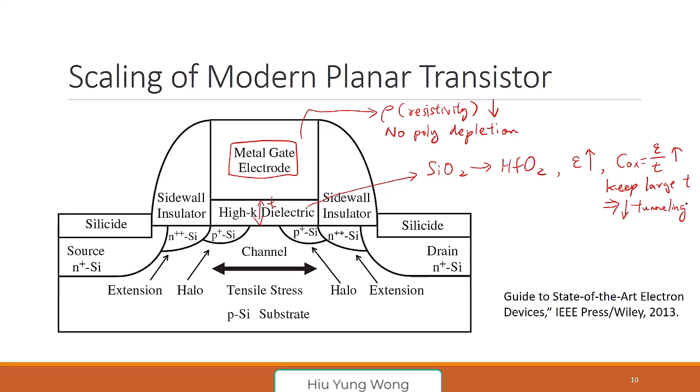And then for the rest, I won't emphasize too much. First, we have so-called silicide, again, just to reduce the resistivity. You let metal react with the silicon. Just know that you have silicide. Silicide is like default now, right? Halo, extension, the extension, right? Actually, this paper has some problem. It is wrong. This one should be N plus, this should be N plus. So I think this book has some typo. You actually have a more nicely doped region here.